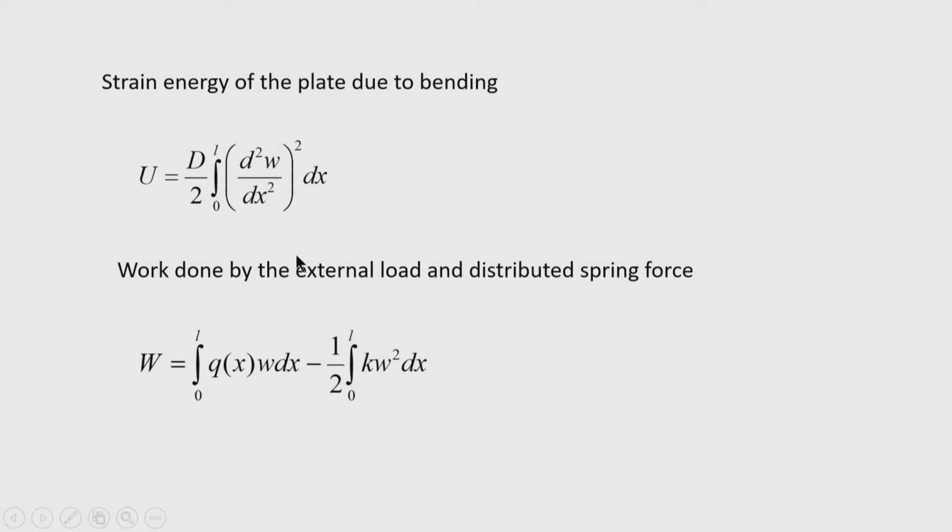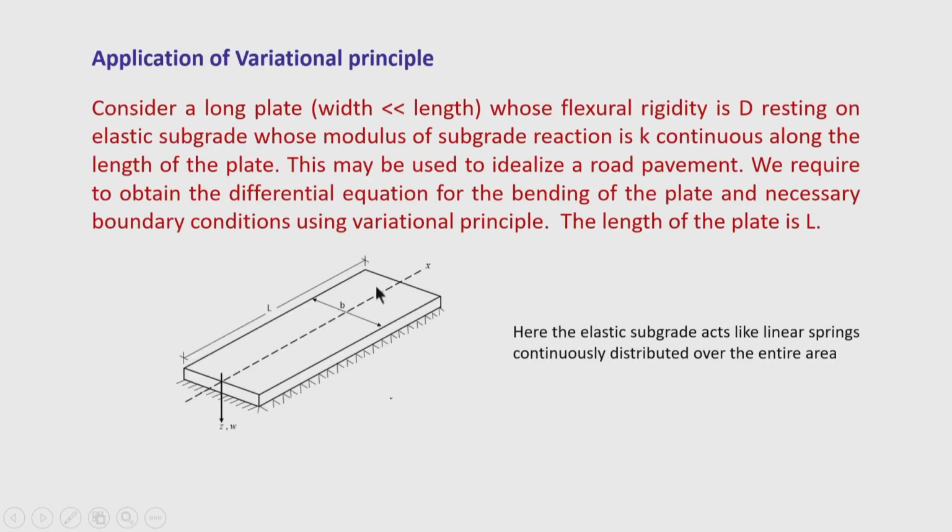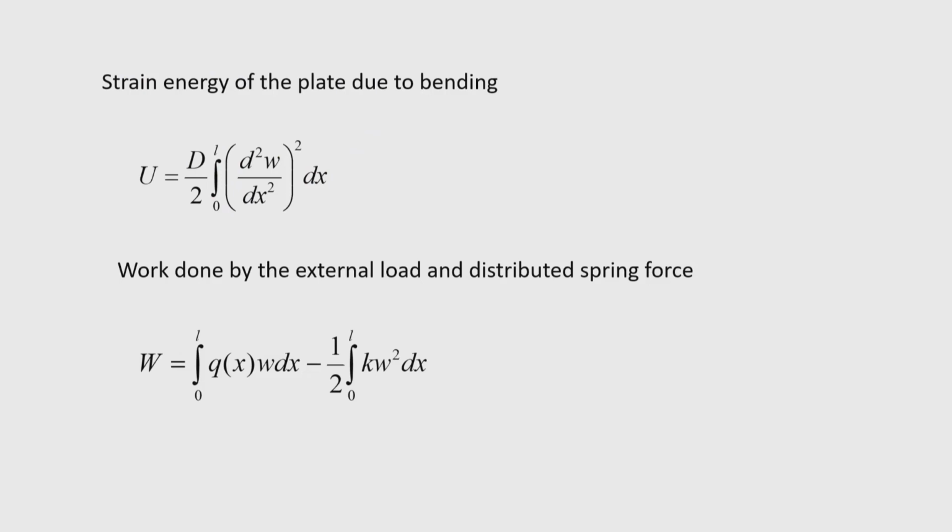Then the work done by the external load. What are the loads on the plate? Suppose some distributed load is acting on the plate. Here we have taken a distributed load acting continuously along this plate, or it may have a discontinuous partial distribution also, it does not matter. But in that case, we are taking that the load is continuously distributed along the length of the plate. So, the work done by the external load is integral of q(x) w dx.